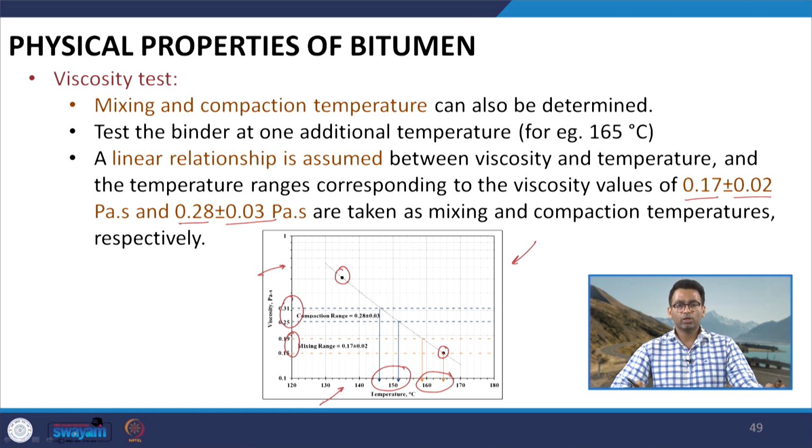In the case of modified bitumen, even at such high temperatures, they may not be purely Newtonian in nature. So, their behavior can be dependent on the shear rate, and because of this non-Newtonian property, the equiviscous method may not give a true replication of the workability characteristics achieved in the mixing plant. In the case of warm mix binders or warm mix additives, some of the warm mix technologies do not necessarily reduce the viscosity of the bitumen.